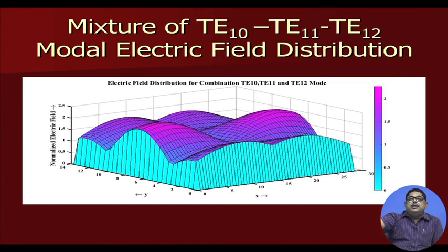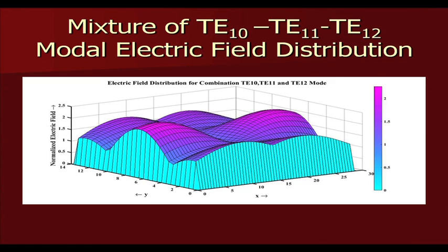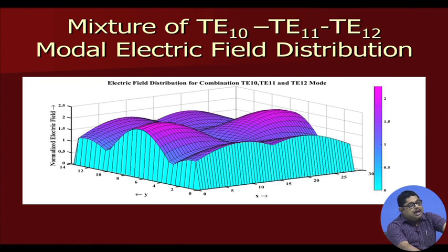So, a particular field may be, suppose in a coaxial transmission line, you can have all the modes possible, TEM, TE, TM, all of them can be possible. In waveguides you cannot have TEM, and if you see the actual field distribution, you will see something haphazard. But if you break it into these components, you will then understand how much of TE, how much of TM, and which type of TE also have various numbers. These two numbers give 2-dimensional modes. So, various numbers are possible. With that you get all the real-life signals. So, if you understand modes, you can easily break the fields into these modes and then your analysis will proceed.